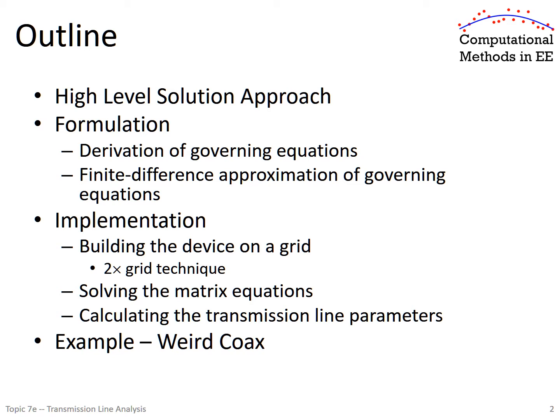And then once we have the answer, we need to do some post-processing to calculate distributed inductance, distributed capacitance, characteristic impedance, effective refractive index, visualize the fields, etc. Given that, then we'll discuss implementation and some subtleties that are really specific to working in 2 dimensions and solving the equations and how to post-process them. And at the end, I'll give some examples. And these examples are useful because these are things that you can try to simulate and duplicate the results in the lecture here. Okay, now we're ready to officially begin.